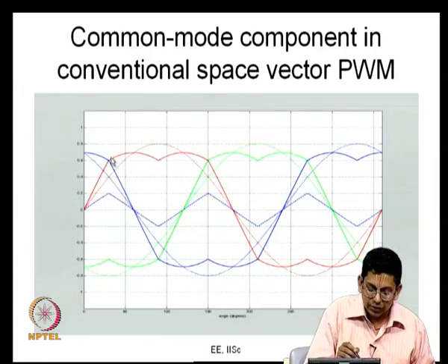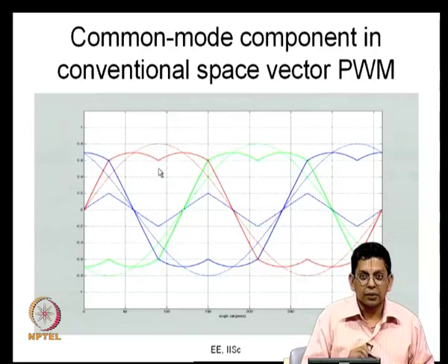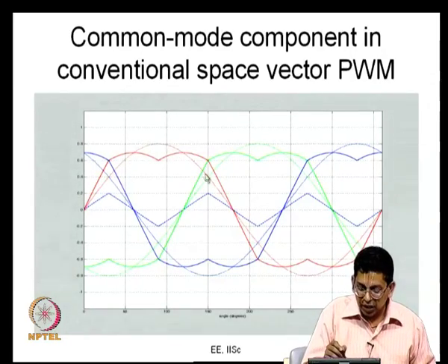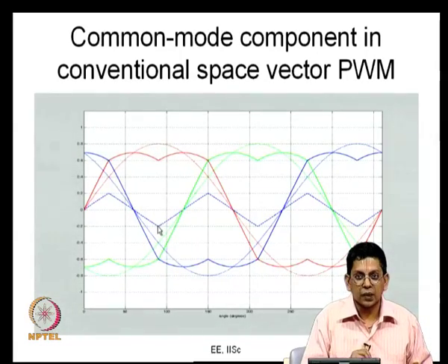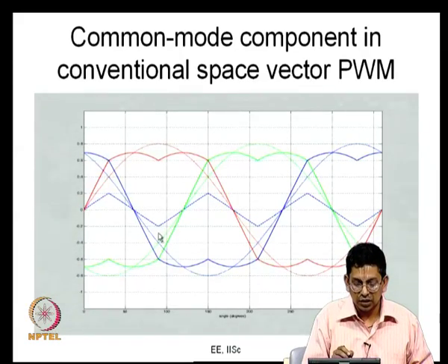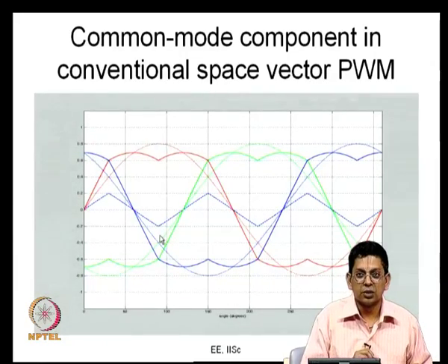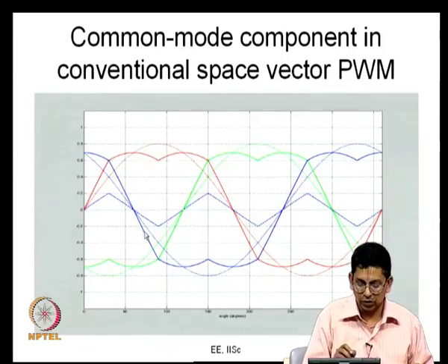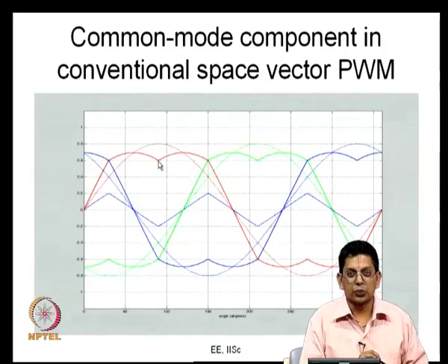So, you can see that here also, and what happens is then it becomes the same value, and here it is negative peak. So, when MR is having its positive peak and it is equal to Vm, MCM is having its negative peak, and how much is this? This is 0.25 Vm, this is minus 0.25 Vm now. So, Vm sin 30 is 0.5 Vm, so this is half of that, so minus 0.25 Vm. So, what you have here is something like 0.75 Vm.